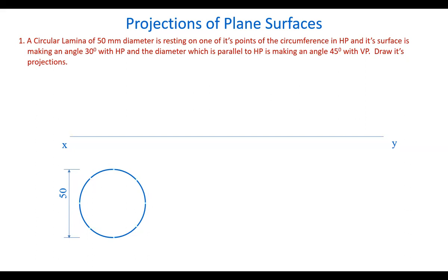So here we divide this circle into a number of parts and mark them like this. Okay. So it is divided into 8 parts only here to avoid congestion. So better you take 12 parts. Then you get 12 points and you will be getting a smooth curve.